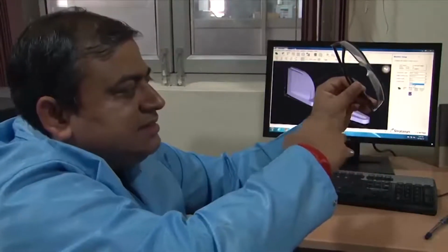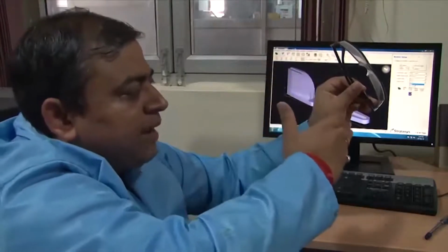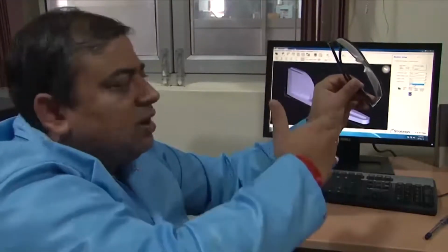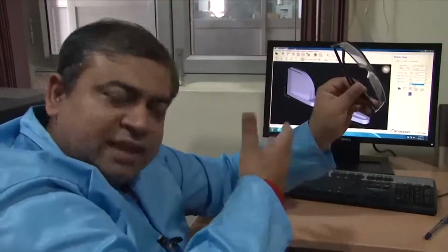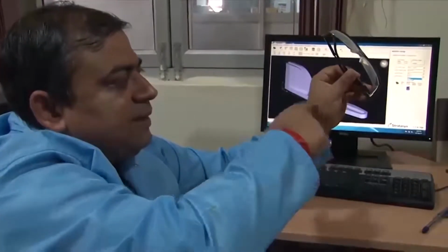So you can skeletonize the support material in a manner so that it can do its job at a certain angle also. Okay. So this is called a smart support, which actually saves the material. So one option could be to just give a thick grill like this in a perpendicular manner.